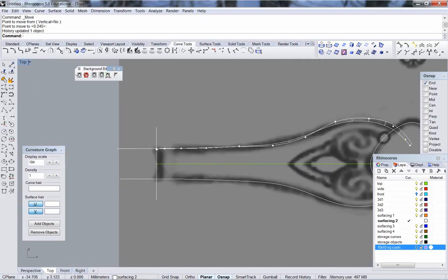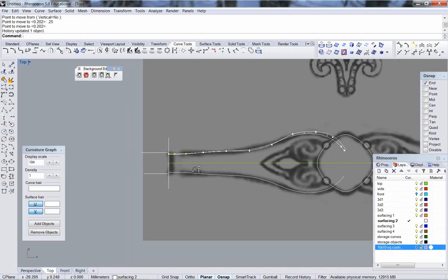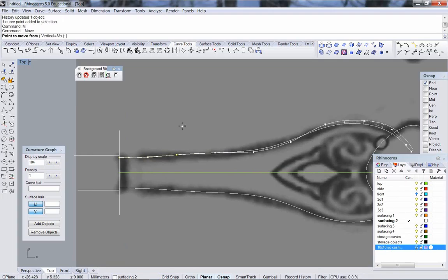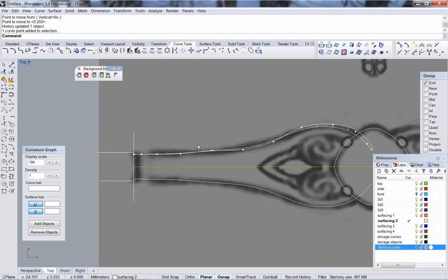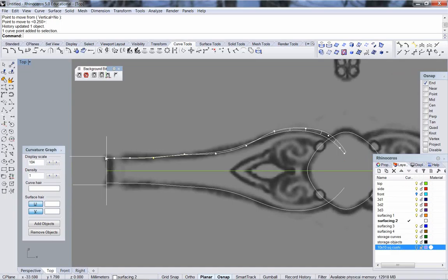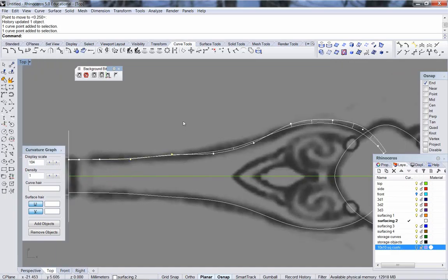I really do feel like this is probably too wide, so after all that effort, I do want it to be a standard distance, so from 4 millimeters I want to take it down to 3.5, so I'm going to move this 0.25. Notice that I selected both of these points because they are in a straight line relationship with this, which maintains smoothness. I want that smoothness so that when the ring wraps around and touches itself on the bottom, they line up in a smooth fashion.